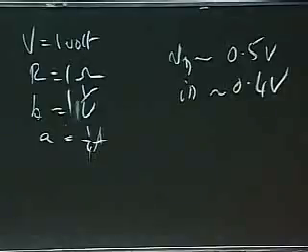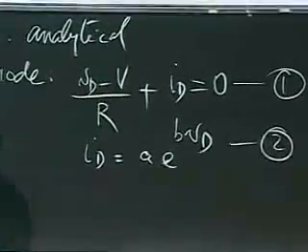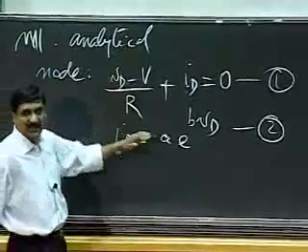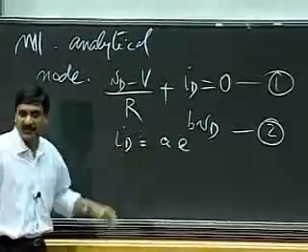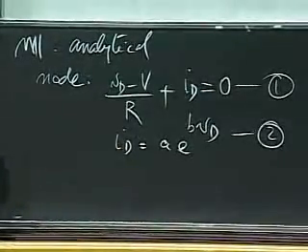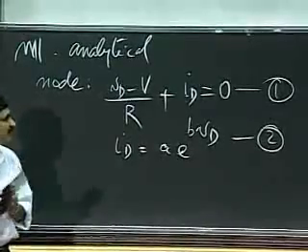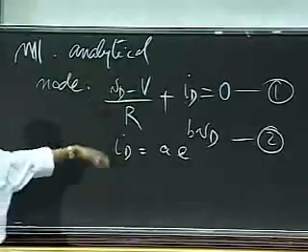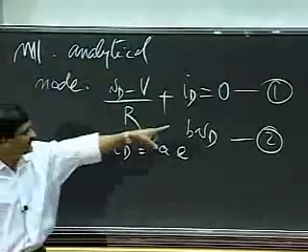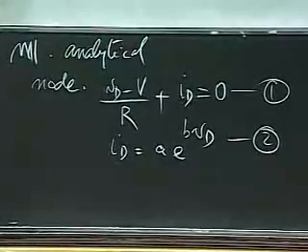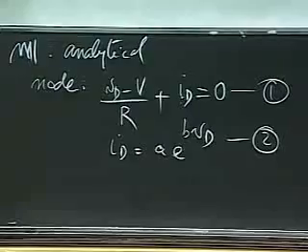In 6002, we don't dwell on working too hard to solve equations of this sort. If you cannot substitute this in here and solve it directly, we don't ask you to go and learn numerical techniques to solve it. But just remember that you can use trial and error, or back substitution and other techniques that you'll learn in future numerical methods classes and apply them here. For here, we can stick with trial and error if you like. For these values, VD and ID are 0.5 and approximately 0.4. We're done. It's really that simple.